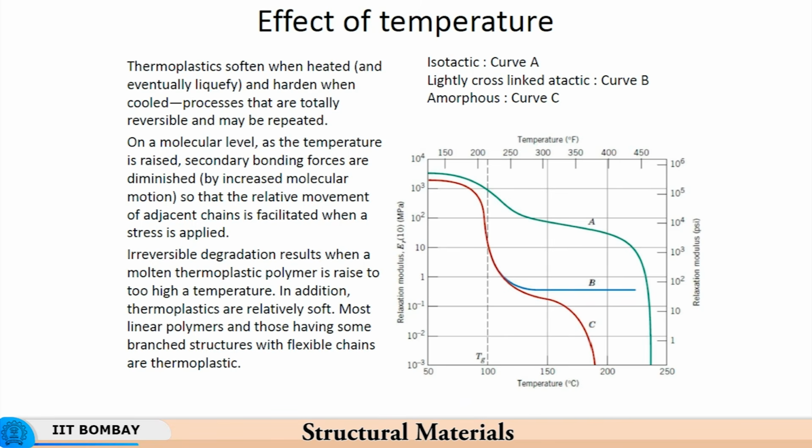But after you have either subjected it to several cycles or left it at high temperatures for a certain duration of time, these chains break up into smaller chains, and therefore you no longer have the macromolecule or the large sized polymeric chain that you had earlier.